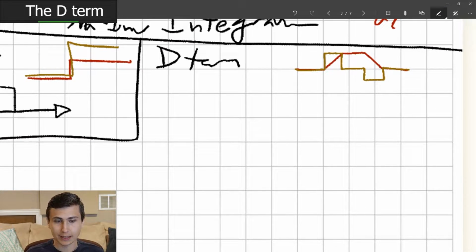All right, let's draw this differentiator. Now, this is actually going to be a differentiator with a filter built in. Real differentiators without a filter, unfiltered differentiators, have this nasty tendency to be incredibly unstable. And so we're going to add a couple extra resistors to this differentiator to make it both non-inverting and to make it a little more stable. All right. It's basically a filtered differentiator. And we're adding a gain stage at the end, and we'll get to that in a moment. We're going to start with our input.